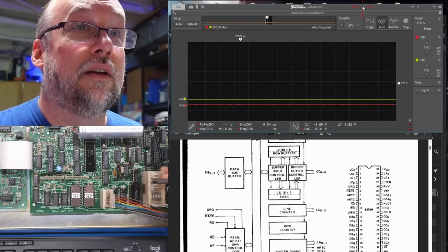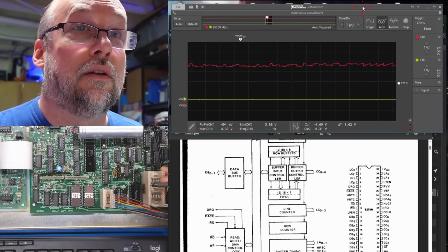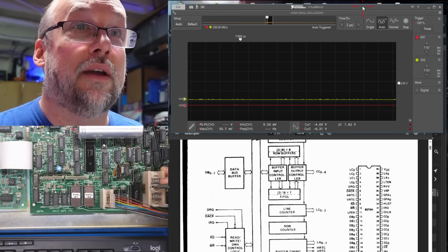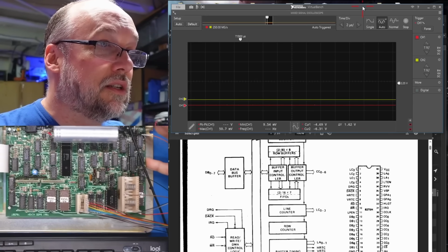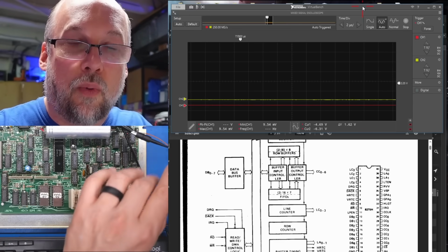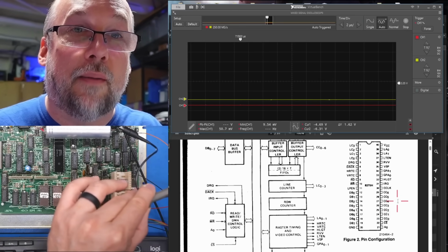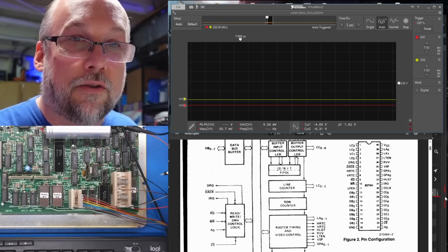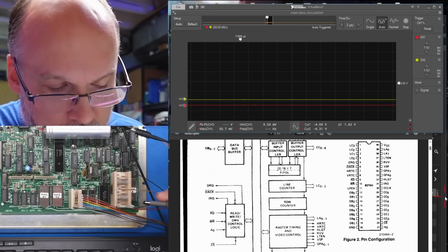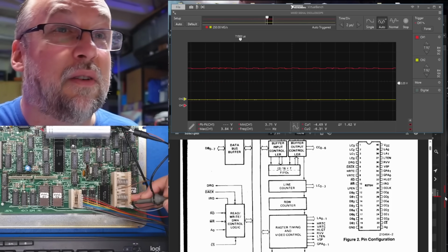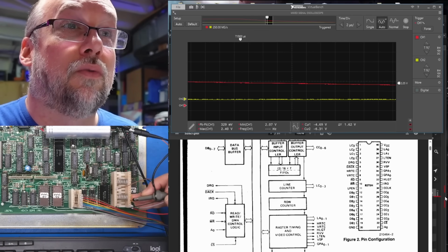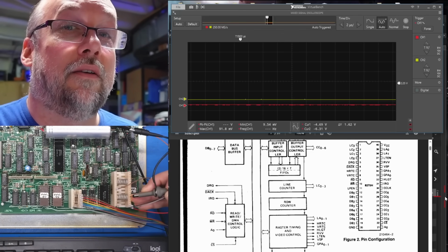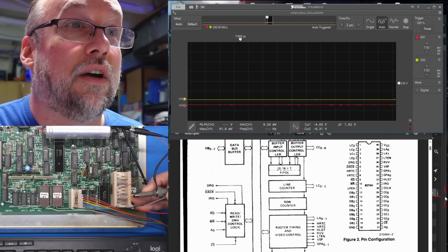DT-AC, that's high. Pin 7, horizontal, nothing. Pin 8, vertical, nothing. Read is high because that's an input. Write is going to be high. Well, I can't read it because I have a wire on it. Sorry, you can't really see what I'm doing because I'll move that over a little bit. There's no point looking at the data bus stuff because there's nothing going to be happening on there. We can take a look at these C counters there. So let's start above the chip select line there. Okay, nothing. Nothing. That's pin 23, 24, 25, 6, 7. 7 oddly is just stuck. Low.